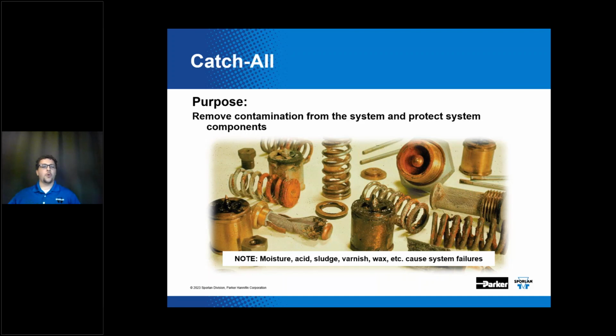And another thing we say is that the TEV is the second best filter in the entire system. And as you all know, you do not want your TEV to get plugged up because it's acting as a filter. So that's why it is critical to get your contaminants out of the system.